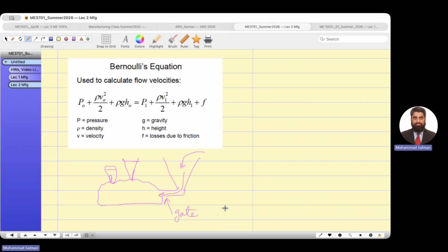Like we go to the subdivision, we have the entry gate. So it's an entry gate when the metal goes inside the casting. And then you have a parting line here, the lower portion and the upper portion, and then you see the sand casting. And now after these are the risers.